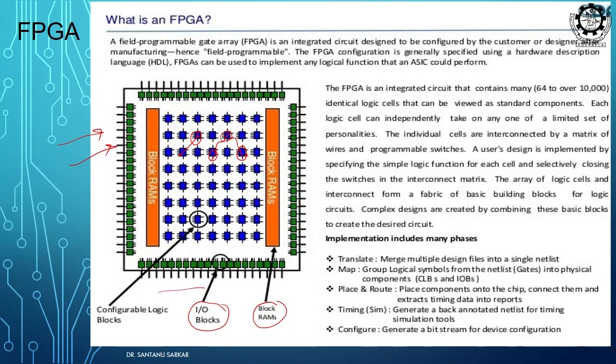So, you can implement anything, you will be having logic gates, you will be having PLA structure, array structure, AND plane, OR plane. Okay. So, any function, if you recall, from your K-map, you could represent them in sum of products or product of sums, right. Two representations were there, right. So, if you have an equation, you can do it here using AND plane or OR plane.